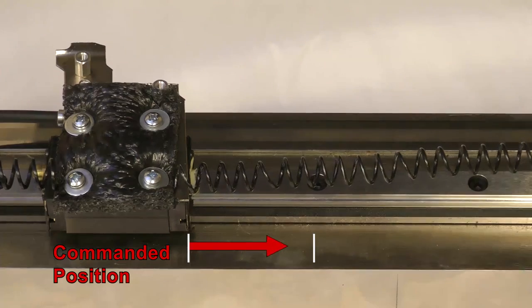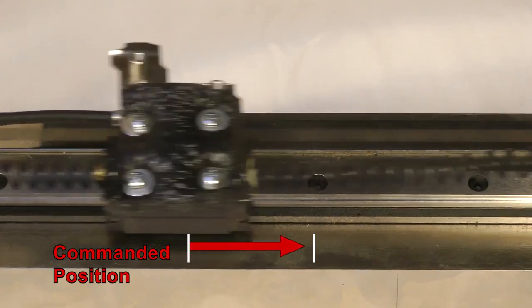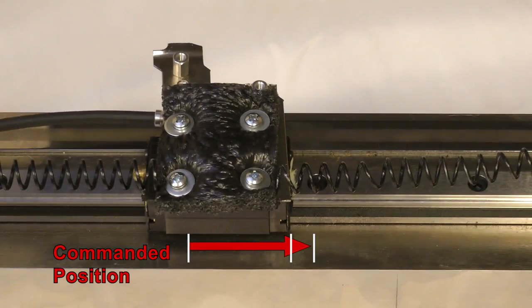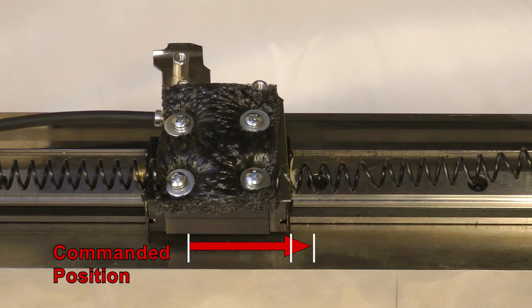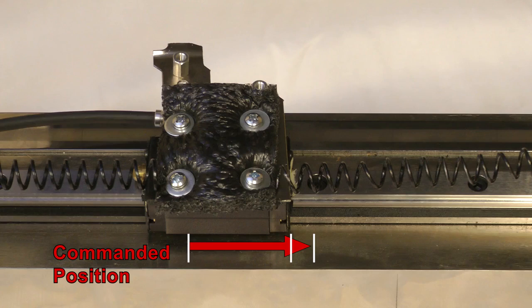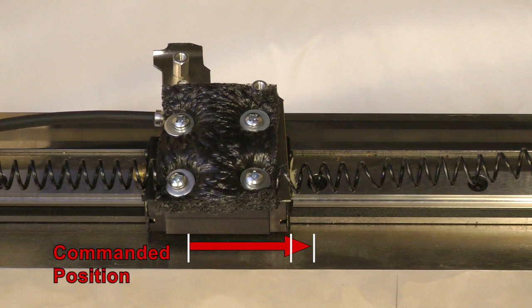Let's now add in an external force in the form of friction. See how as I attempt to move the motor, the friction in the system is resisting the motion, causing my end position to no longer match the ideal position. This is the main issue with microstepping. Because the two phases fight one another to control the stepper motor's position, if there are any external forces, the motor settles at a position which is not the desired one.